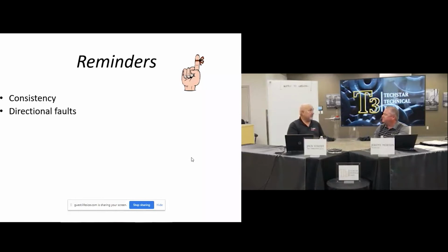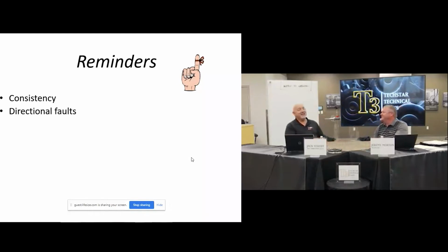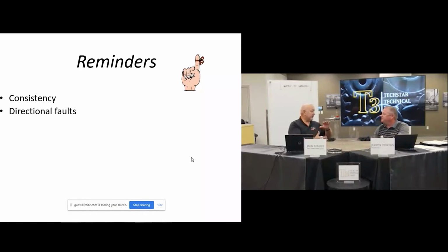Don't quote me on these prices, I'm just going off the top of my head. But you can get a triaxial for, let's say, $150 for each accelerometer versus maybe $350 to $400 for a triaxial. So you have only one cable to worry about and one sensor to put on there. Sometimes that works out better for them too.